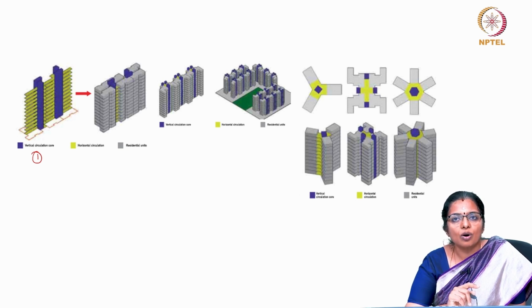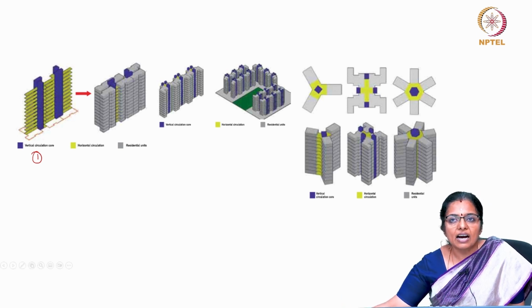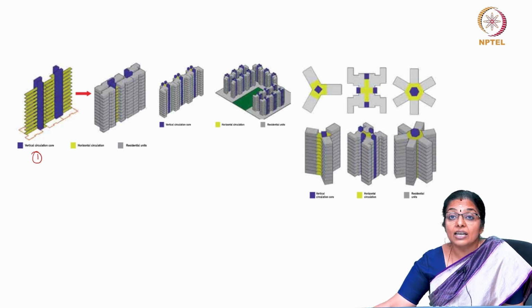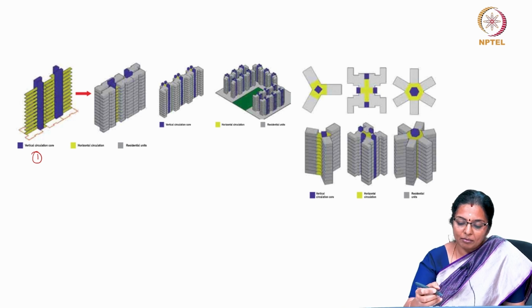Adjoining houses, row houses and group arrangements all continuous along the east-west axis, which tend to create a volumetric effect, are advantageous, as are the high masses of the building. So, you need to look at various other things like, how do you design for various climate types and what is your constraint. So, if you look at hot dry climate, you must have compact and massive design.